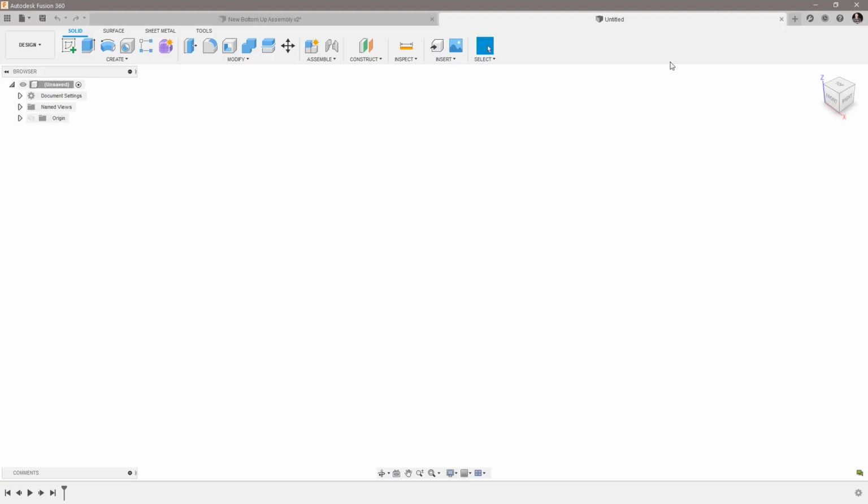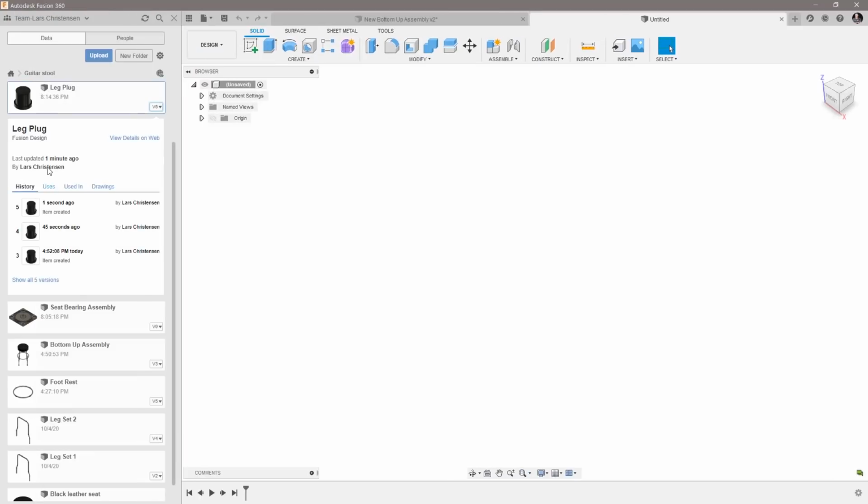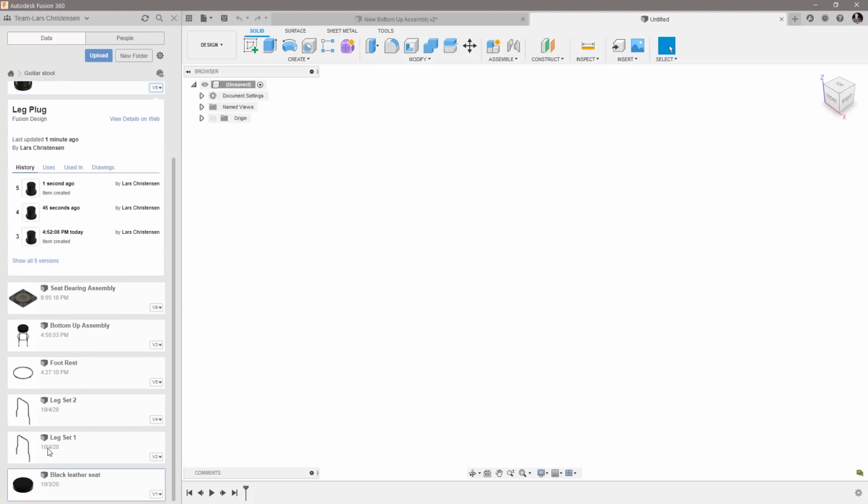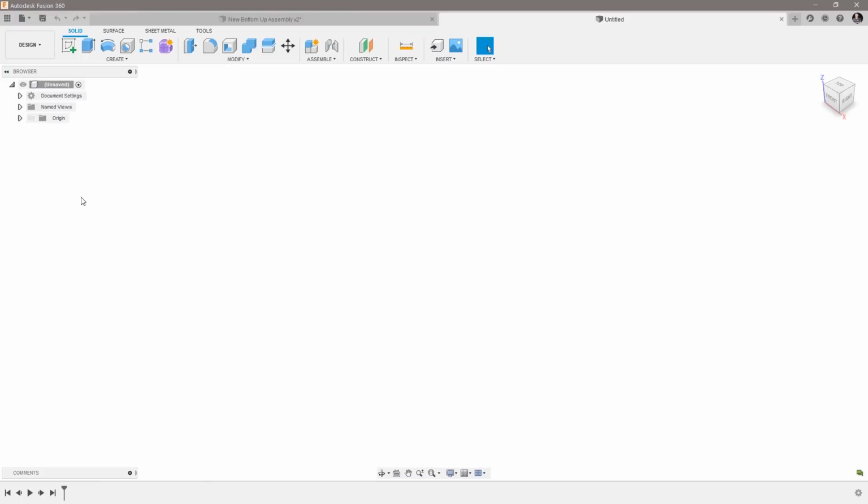What we're going to do is turn this into an assembly right away, but we're actually going to build our design within that, and then maybe also add some of the other components in here. The problem with the bottom-up that we just looked at is that you have to build all the different files in relation to each other, but in separate files where you can't really relate them to one another. What top-down lets you do is do it in relation to one another.